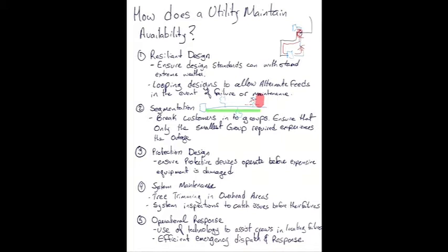All right, fuse links are cheap and we want them to blow. Transformers are more expensive. We don't want them to go. Some automated pieces of switchgear could be $50,000, $60,000, $80,000. We certainly don't want that damaged if we can protect it with an inexpensive fuse link.